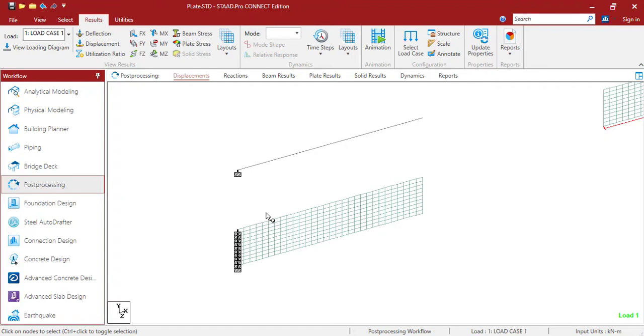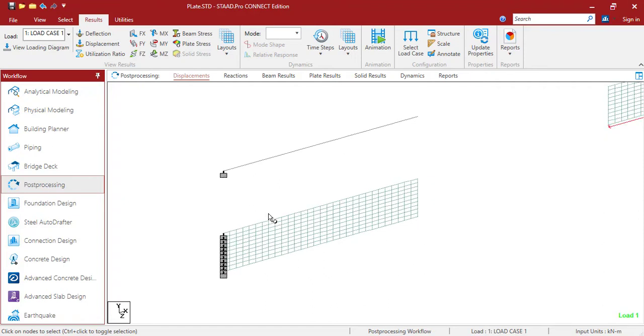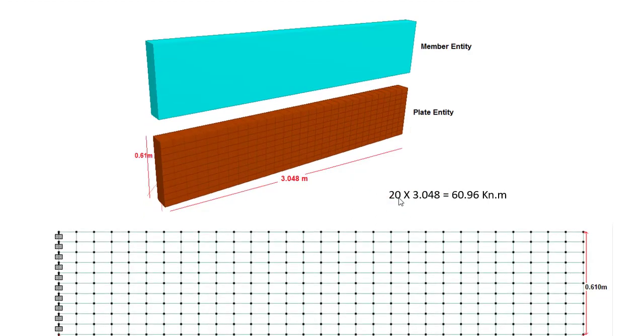Okay, now see, in case of plates, the bending moment at any section is the total moment developed about the neutral plane due to the longitudinal stress exerted by the infinite number of fiber sections at the said locations, right? So let me just give you a quick understanding over here. See, our plate is divided something like this, right? And here is the neutral axis. Now, as you know that in case of the beam, the upper half of the neutral axis experiences the tension, right?